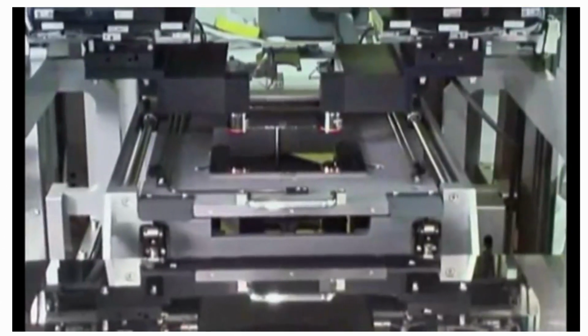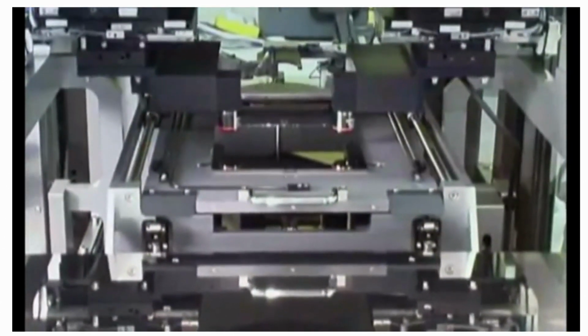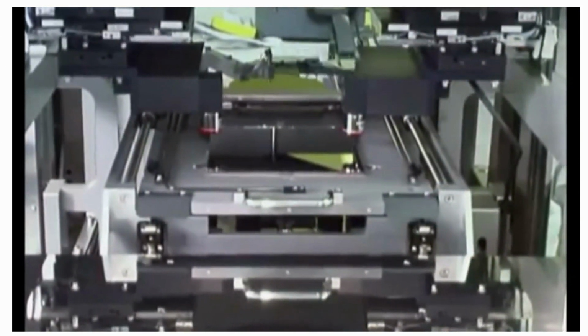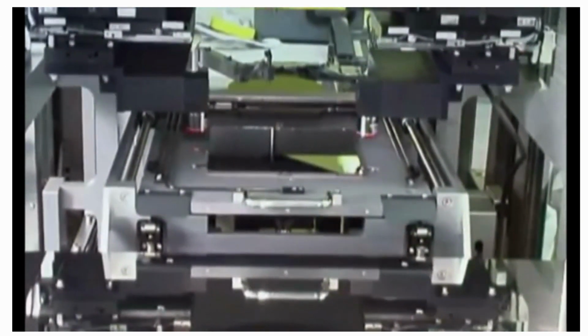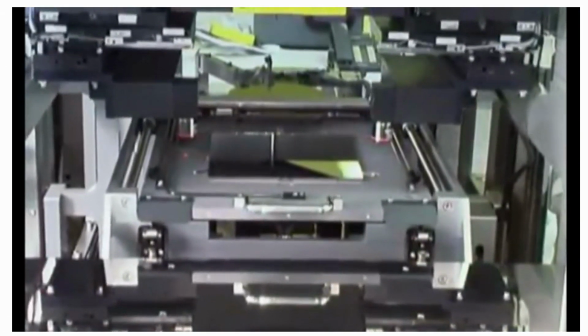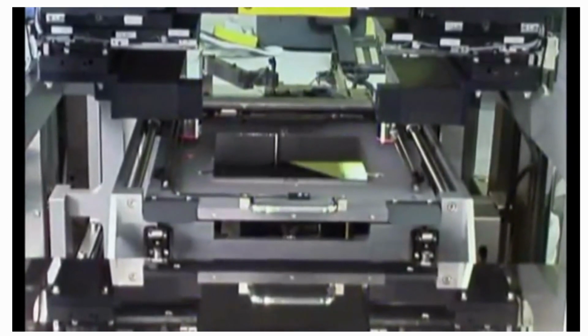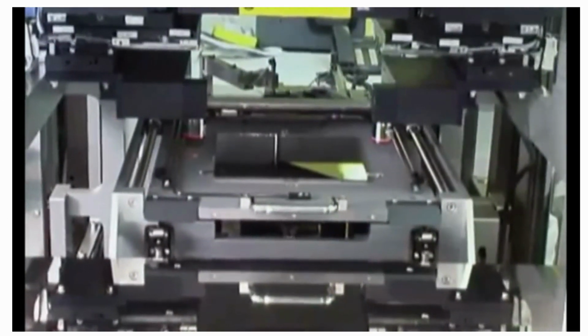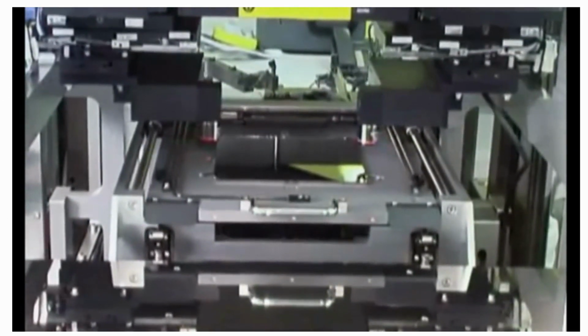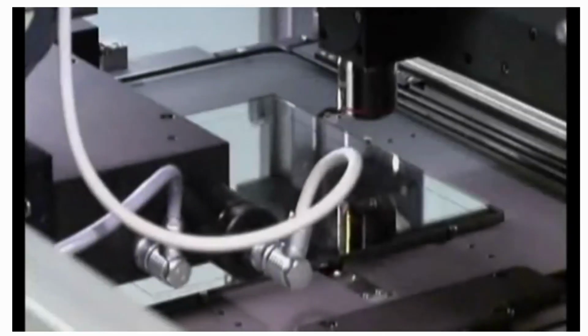No other mask aligner on the market offers a higher degree of alignment accuracy than the MA200 Compact. With the use of the recently developed and patent-pending Direct Align option from SUSS, the mask is aligned directly to the wafer, guaranteeing an overlay accuracy of up to 0.5 microns at 3 sigma.